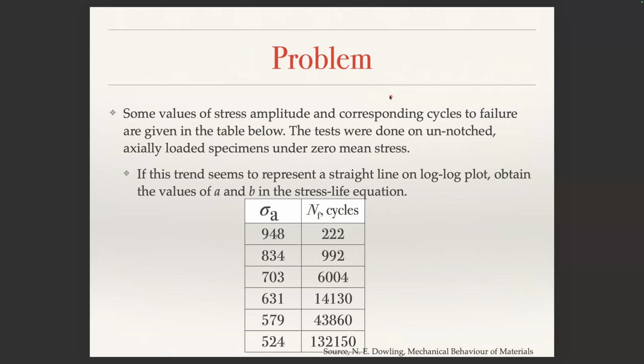Yes, sir. So right now what we have done is, by knowing the SUT, that means ultimate tensile strength, we have constructed an estimated SN diagram. We have not really taken the values of failure from some test data, but by knowing SUT, we understand it is 0.5 SUT and applied the correction factors and so on. Correct? Now, instead of that, if you have test data,